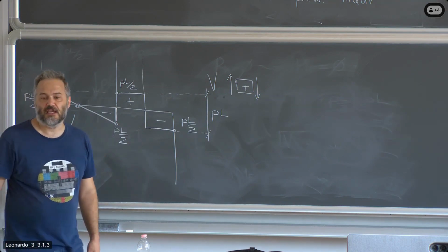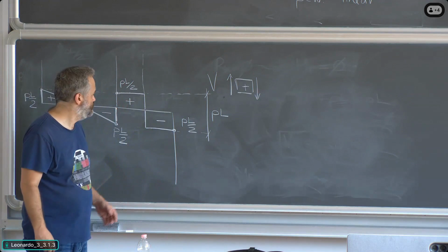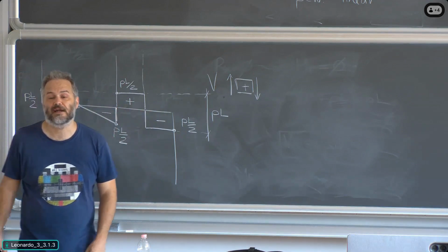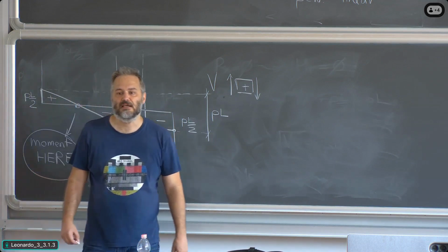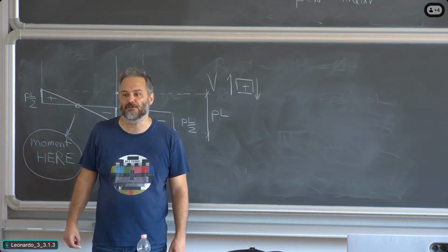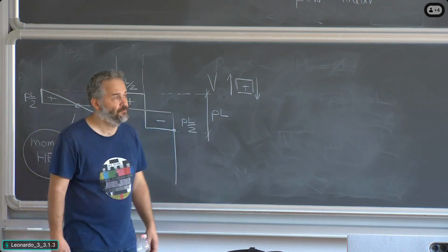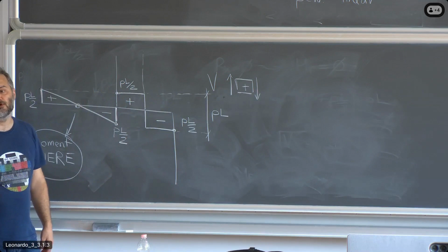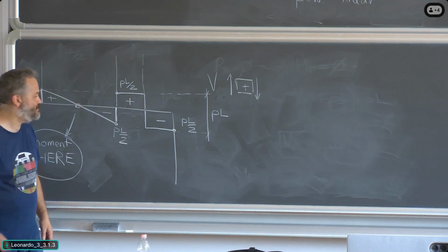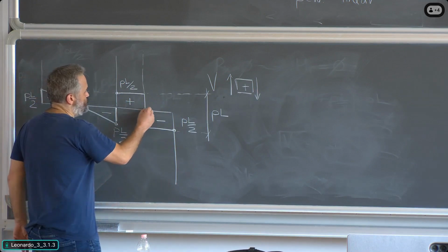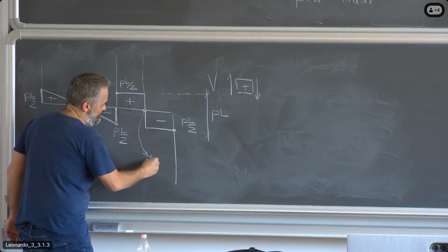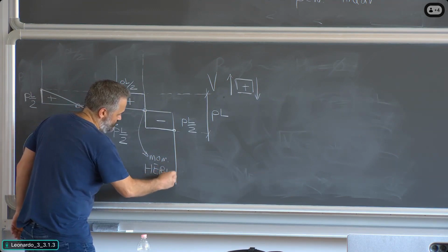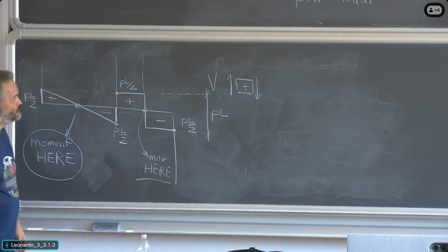Same way of thinking for BC. We already have 2 values of the bending moment available, where at the ends, B and C, we have 0 bending moment. We know because there are hinges there. We need a third value of bending moment. Where are we going to work it out? Mid-span. So, also in this case, moment is calculated here. Okay?